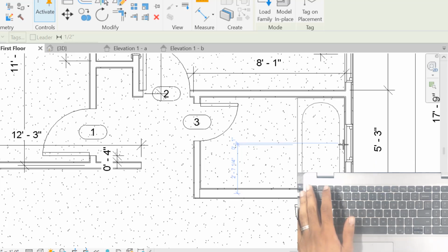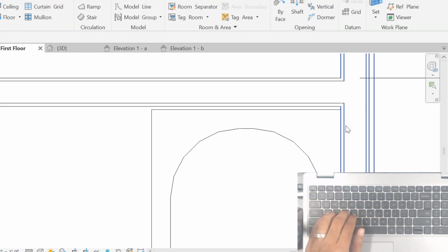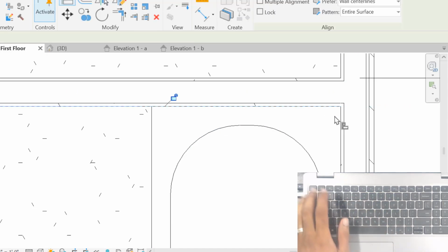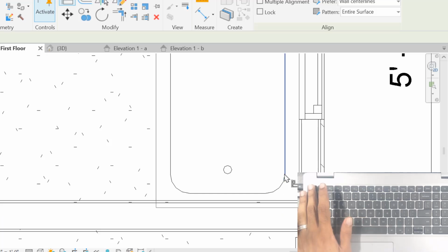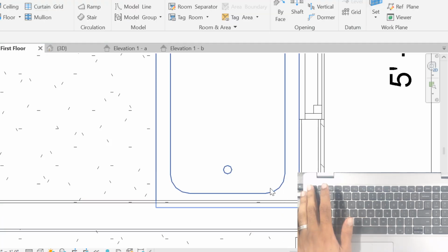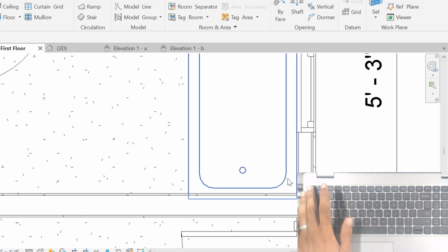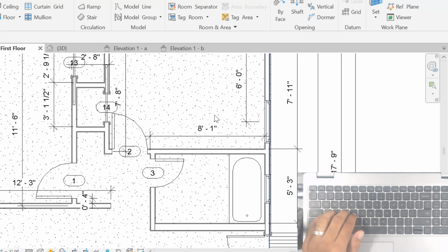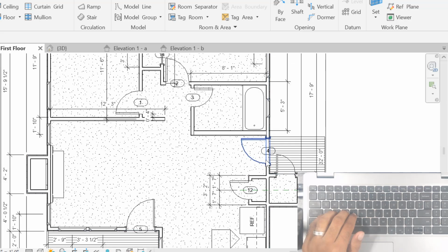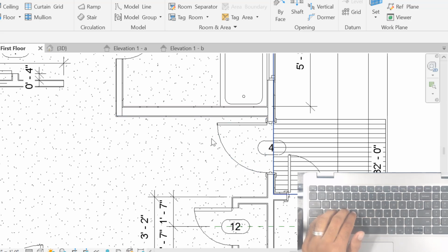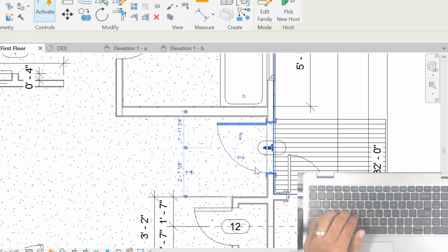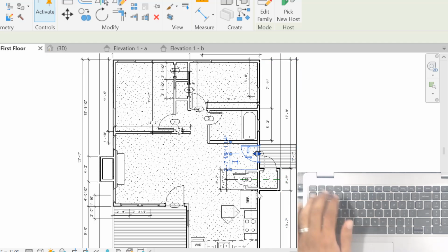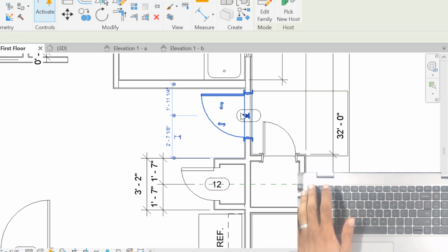And as we place it, I want it align AL to this corner. Tab select to align to this corner here. And it automatically is bigger than the wall that we have right now. So we have two choices, either to shrink our bedroom or to shrink this circulation space. I choose to shrink the circulation space because our bathtub can simply move the wall over, but our bedrooms shouldn't get smaller. So let's go ahead and move this over.